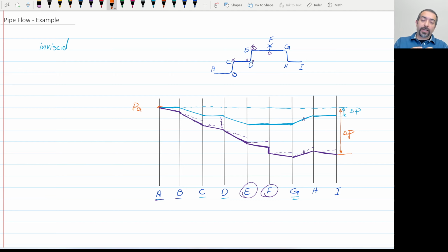Okay, and again, we can very easily calculate once we know the length of each segment of the pipe, the diameter of the pipe, the density and viscosity. We have all the tools to exactly calculate the slope of each of these curves and exactly calculate, as much as we can based on the available experimental data, what pressure head is needed to move the flow inside the pipe. But again, as you see, this gives us a little bit of physical intuition of what happens and where, if you do it very accurately, we're going to have the maximum losses.